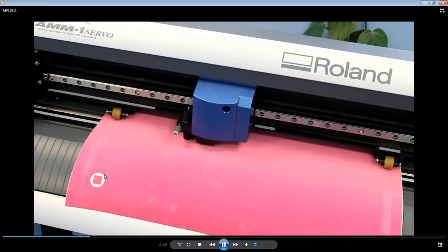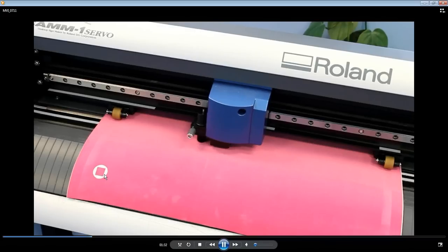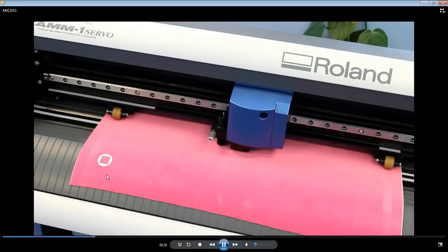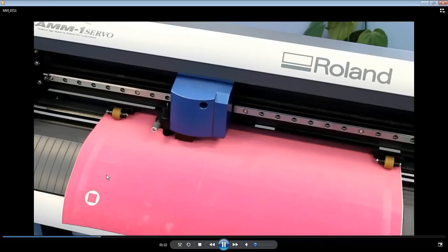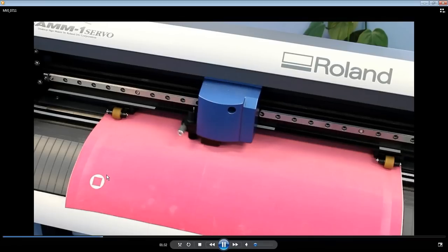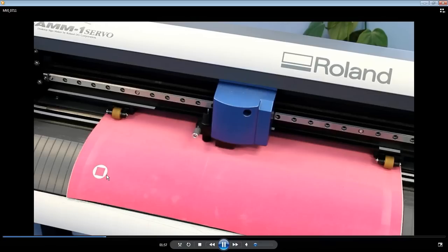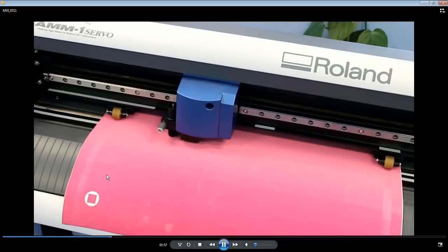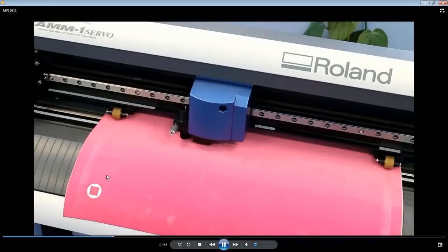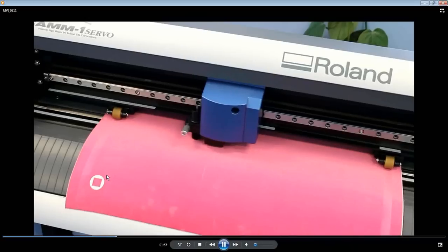And the test cut here also, anytime you're working with a new blade, an older blade, a different offset to it, and most especially a new material. Say on this machine here I've been cutting eco film earlier. I definitely want to go back and test it when I put in a new material like sticky flock here, because my eco film with a newer blade, say a 45-degree brand new blade, it'll cut at about 50 grams force. I don't need a whole lot to cut that. Whereas the sticky flock here, I was cutting it at 160 grams force with a brand new 60-degree blade.